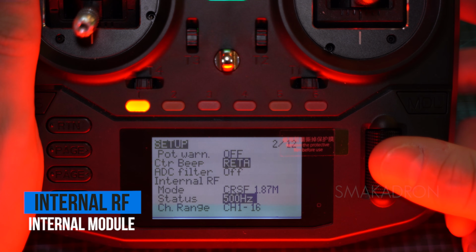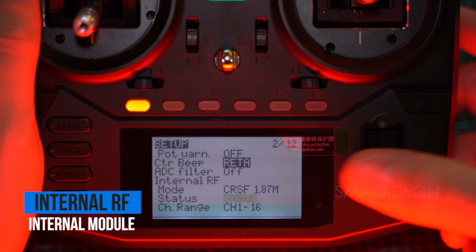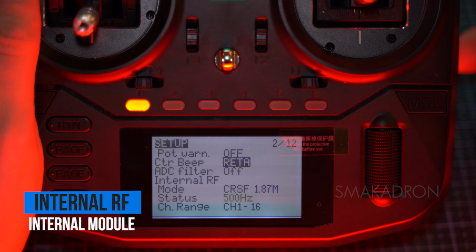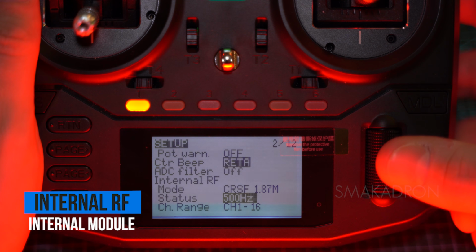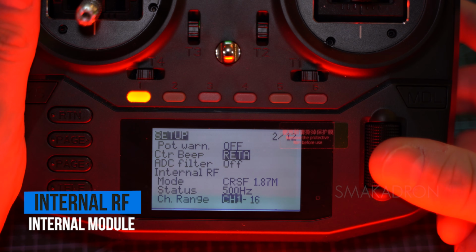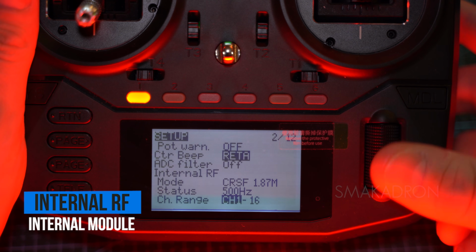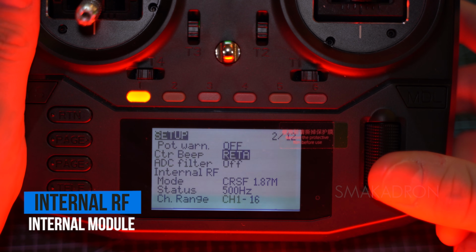Status displays the packet rate settings of the transmitter module. I have it set to 1000 Hz, which I would say is a very high packet update rate that allows for fast data reception at the receiver. It's very useful for hardcore freestylers and those who are into racing. At 50 Hz, you can fly very far, but with some latency. We will talk about this in more detail in another video.